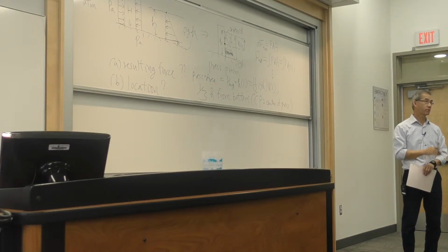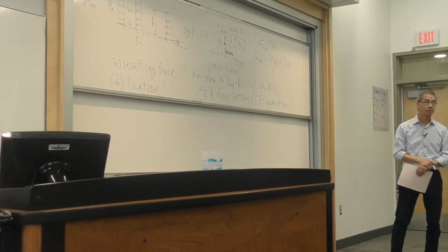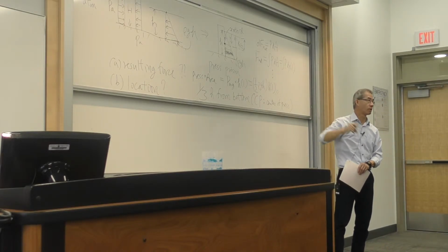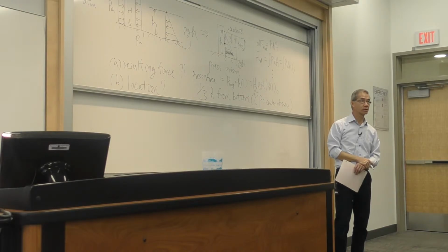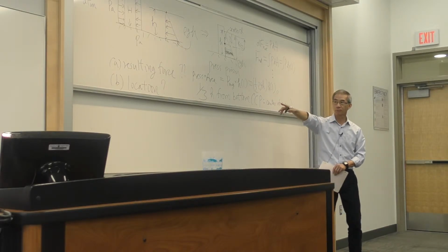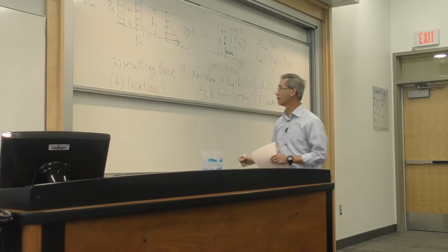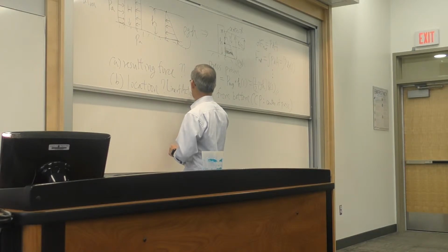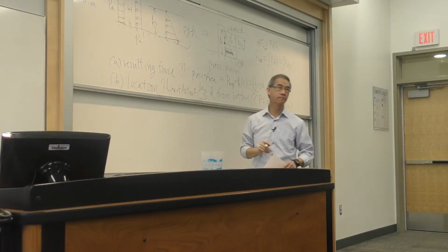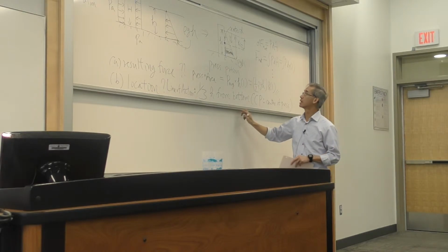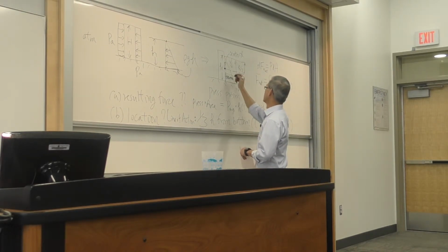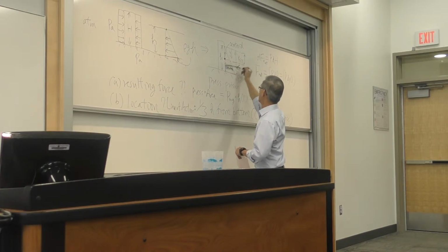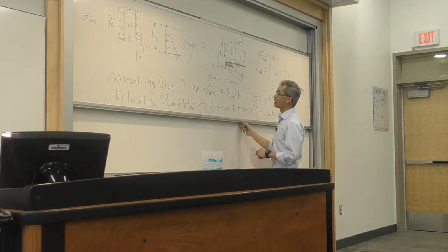Center of pressure, because it's a pressure prism, triangular shape, is weighted more towards the bottom, and hence the actual center of pressure, or the so-called line of action, the location of which this resultant force will act is... I should draw a new diagram.